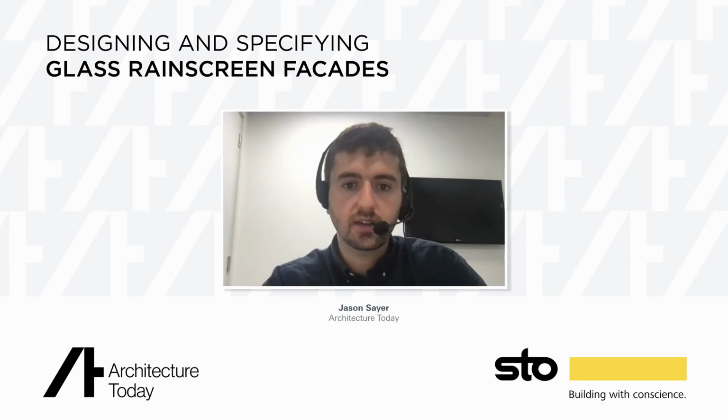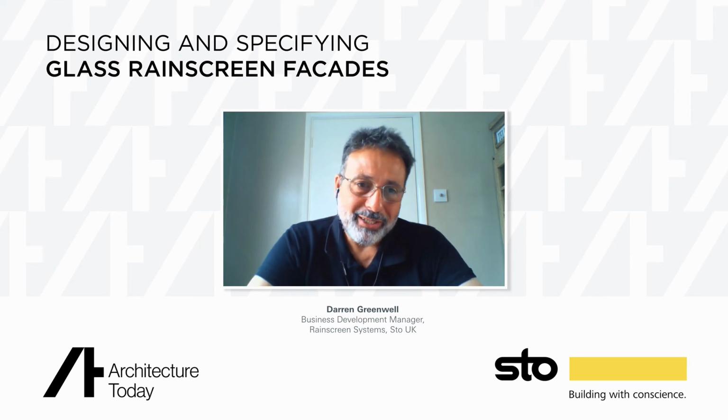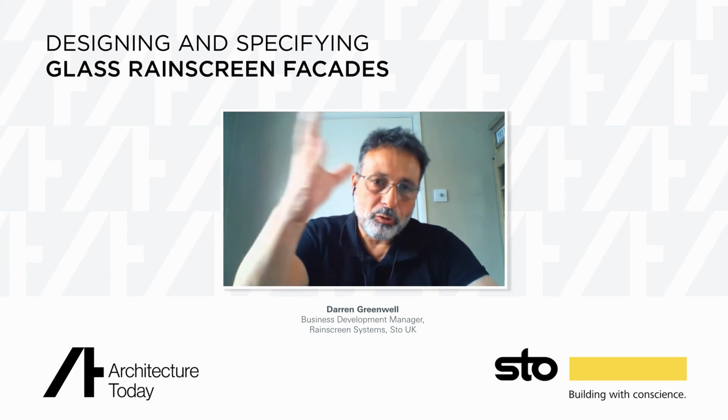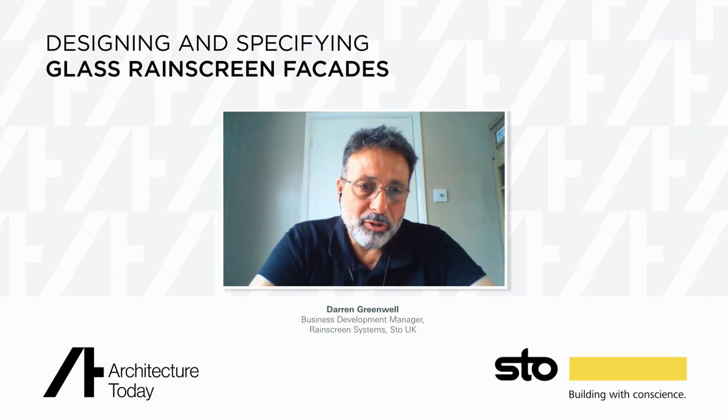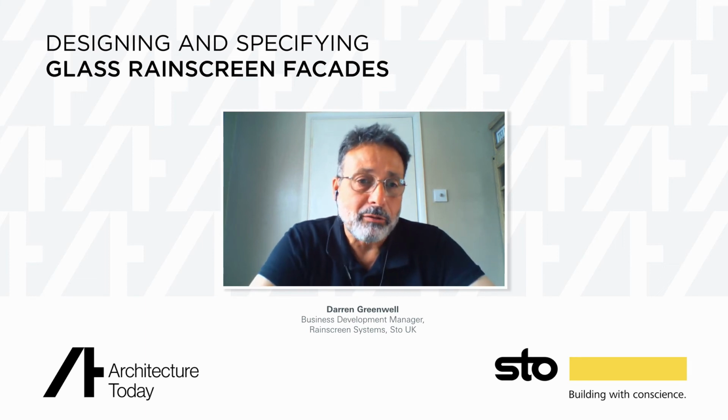What level of impact can the glass panels withstand? With CWCT 76, it talks about impact hard body, soft body testing. Greg will be able to go into the details of that, but we have a YouTube video that shows all of the testing that took place, with hard body, soft body, cranes swinging things at glass panels at a test centre, and you'll see that the glass remains bonded to the back of the panel under impact. So there's no danger of flying glass fragments or splinters coming away.